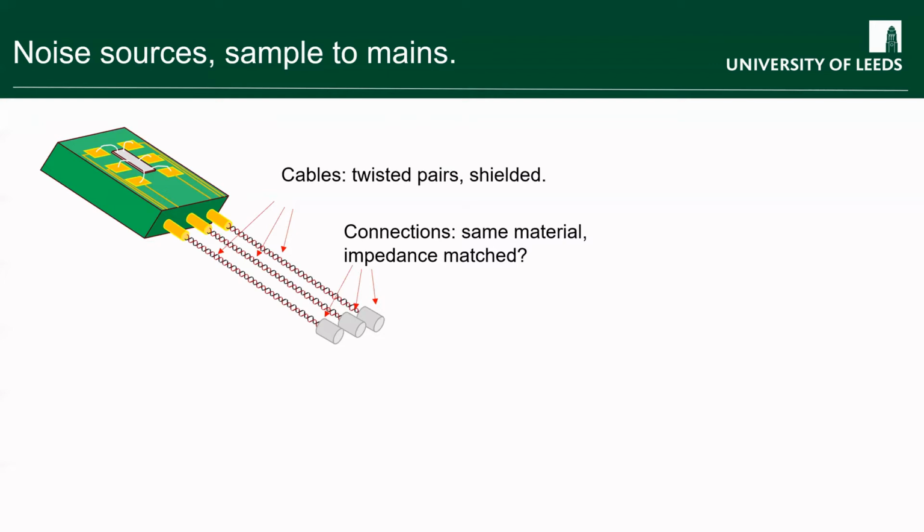In my line of work in low temperature physics, one of the very common ones is that solder superconducts, and when a material superconducts, it doesn't transmit heat very effectively. So as you cool your sample down, typically, because your sample is mounted on an insulator, you're relying on it being cooled by the signal lines, but then your solder goes superconducting and all of a sudden your sample stops cooling. Or else you generate additional voltages because you've got contact resistances in there that are not linear or are temperature dependent. So there are all these different effects that can potentially come in to mess your experiment up. And everywhere you're introducing a higher resistance, of course, you're adding Johnson noise in. And every time you have an insulating tunnel barrier there, you've potentially got shot noise being introduced.